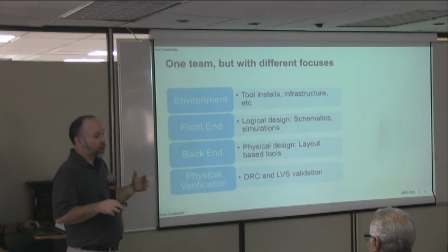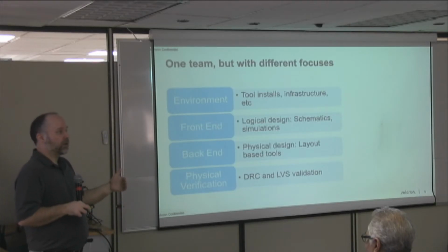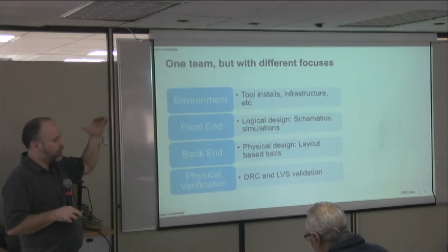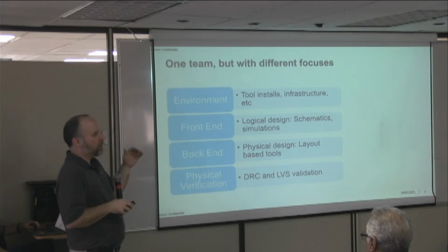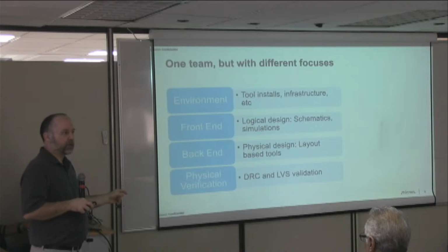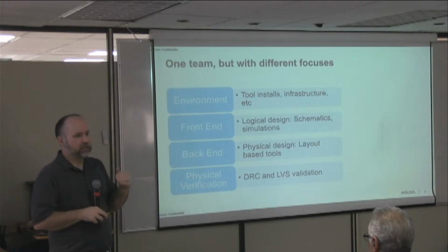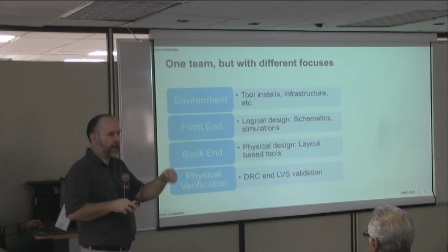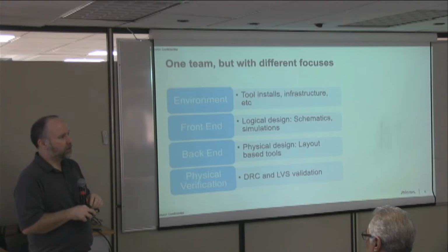And so it's a pretty complicated process, and all those rules need to be able to run, and they need to be able to run pretty quickly. The standard of excellence for a DRAM part is we want to take our full chip, which is a 16 gigabit DRAM, and we want DRCs to run in less than 2 hours, and we want LVS to run in less than 30 minutes. But if it's longer than that, people get upset, right? Because they need to be able to run DRCs, fix some things, run, fix, and you want to have as many of those cycles as you can during a day so that they can meet their schedules.